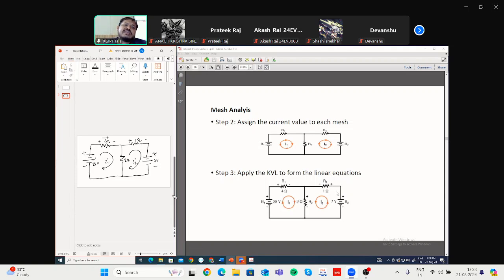Now, if you have any doubt here, because this will be important, how you are assigning plus and minus sign to the resistances, please let me know. Consider a simple circuit. There is a voltage source, there is a resistance. Current will flow from the positive pole of the battery to the negative pole. In that same logic, we are writing this. And also, by other logic, the energy is being absorbed by the resistance. That's why the voltage drop across the resistance will be in opposition to the voltage in the battery. Okay.